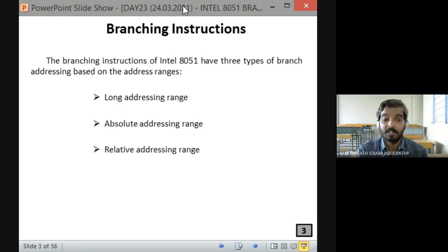What about the remaining bits? Yes, an 11-bit address we are going to use. In that 11-bit address, 8 bits we mention as the lower byte of the address, as the second byte of the instruction. The first byte of the instruction, that means the opcode, mentions the other 3 bits. So totally we have 16 bits: the MSB 5 bits from the program counter itself, the next 3 bits from the opcode, and the remaining 8 bits we mention in the instruction. Is it clear to everyone?